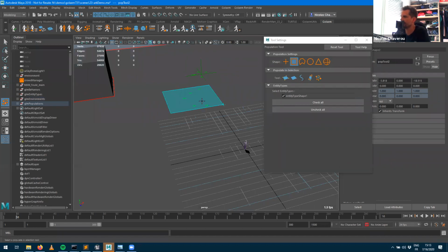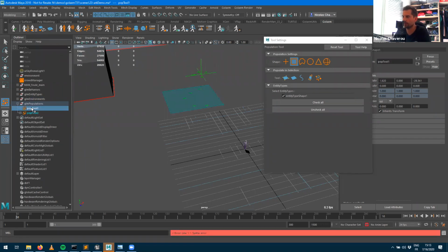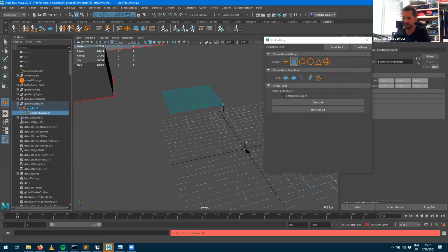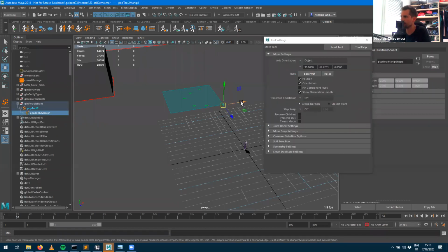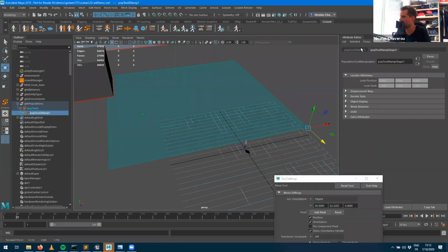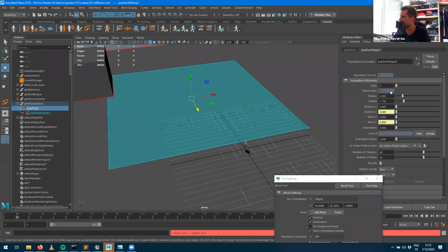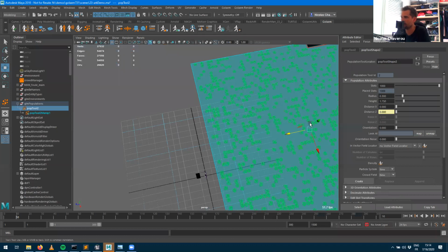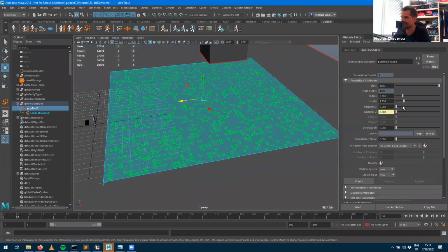So here I'm just going to stick with the box. I'm pretty happy with the box, and let's remove maybe the grid I've been doing here. I can change the size of the box afterwards if I want to by grabbing the manipulator, which is here. And that box can be controlled in terms of how many characters I'm going to put into this. So if I select any node within Golem, they have attributes within Maya, fully integrated within Maya, and I can populate my zone with as many characters as I want to. I can probably change the distance as well.